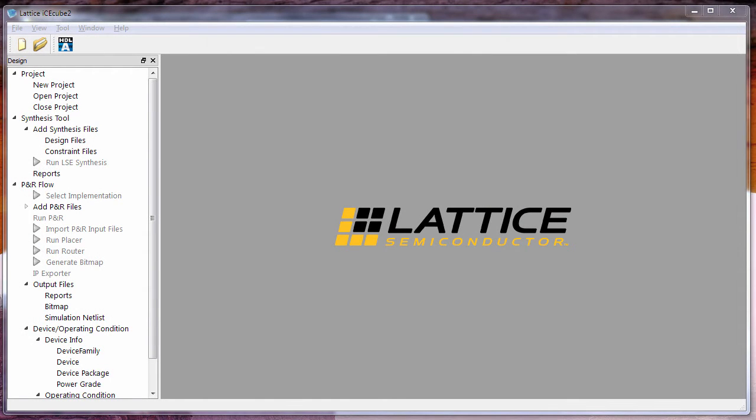Hi everyone, at this point you should have the Lattice IceCube 2 tools installed, and hopefully you've gotten a little familiar with those. The other things you're going to need to download are the Lattice Diamond Programmer, the standalone programmer, for either Windows or Linux, and the virtual COM port drivers for the Go board, which are available on the FTDI website. I will link to both of those in the notes for this YouTube video, but you are going to need to download both of those so that you can both program the Go board and communicate with it.